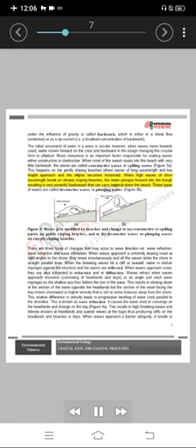When high waves of short wavelength break on steeply sloping beaches, the water plunges forward into the trough, resulting in very powerful backswash that can carry material down the beach. These types of waves are called destructive waves or plunging waves, figure 3b. Figure 3. Waves get modified on beaches and changed to A, constructive or spilling waves on gently sloping beaches, and to B, destructive waves or plunging waves on steeply sloping beaches.